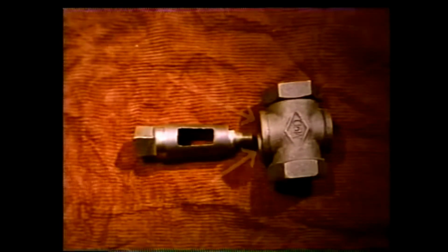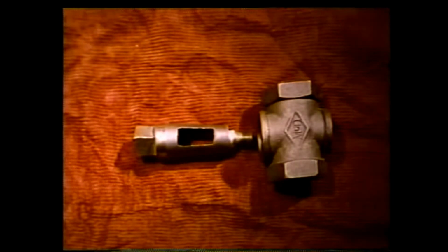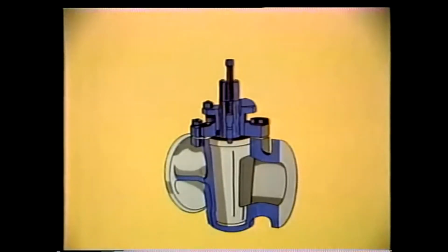The seats on the plug valve are usually built into the body. Many plug valves are equipped with plastic-coated self-lubricating seats. The others must be manually lubricated. This one works just like a cup lubricator for a bearing. To do this, a lubricant screw attached to the top or bottom of the valve is rotated and lubricant is forced into grooves. The lubricant enters the grooves at a higher pressure than the system pressure. This keeps any solid particles in the system flow from getting lodged between the disc and valve body.